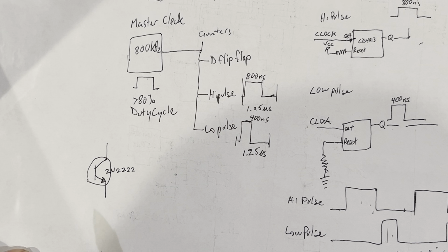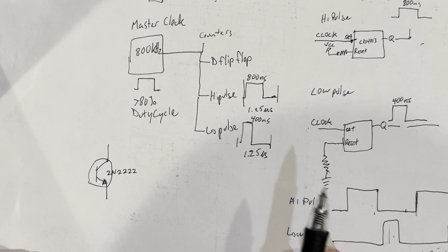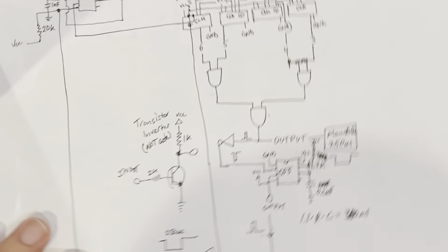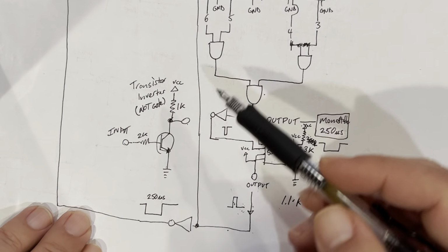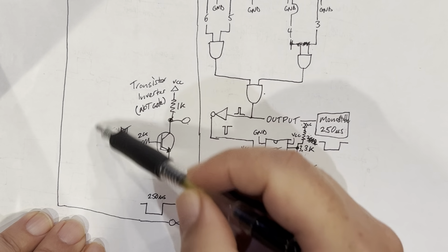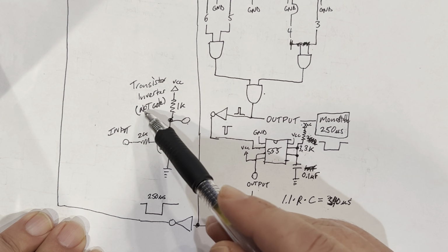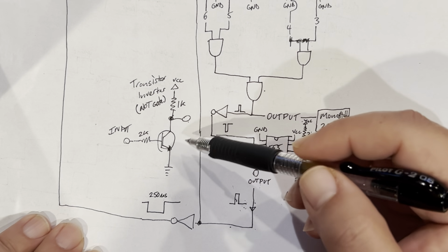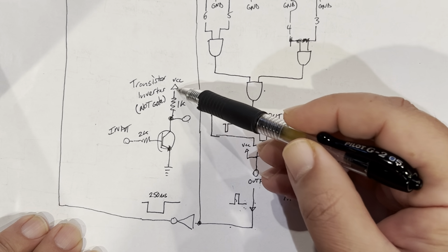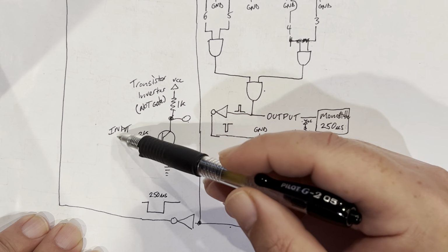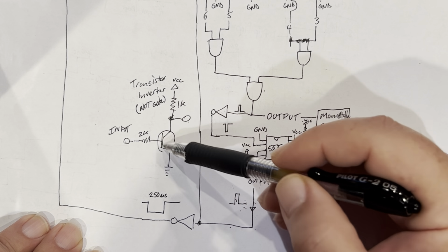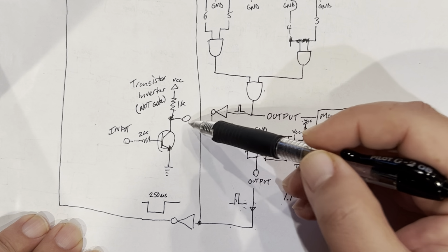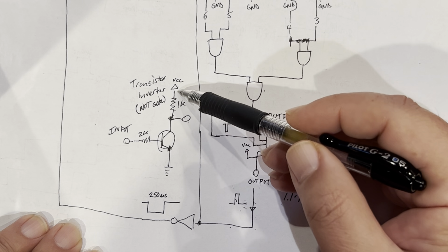And so I've made transistor-based inverters previously. If you could look here from the previous video, I drew it out. This is a transistor-based inverter, and it's a NOT gate. And when you need one NOT gate, and I made them before I had any of these chips, you basically take a signal, that's the input. You put it through a 2K resistor, and the output of this transistor is from here and basically going through a 1K resistor to power.